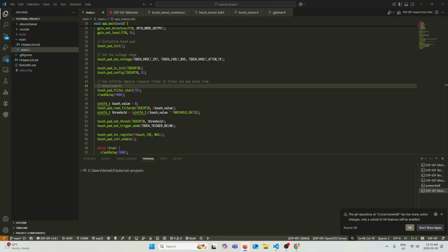So you sample the analog waveform. Of course, it needs to be at the Nyquist rate, so 2 times the bandwidth, or 2 times the highest frequency component in the frequency domain. Signals and systems coming in clutch. One continuous range of analog voltage is divided into a finite number of levels based on the resolution.